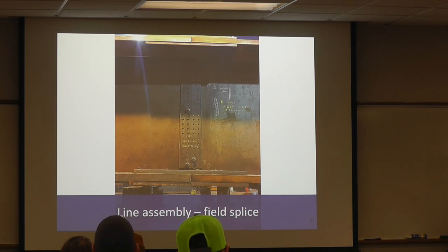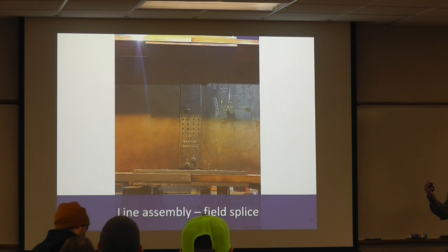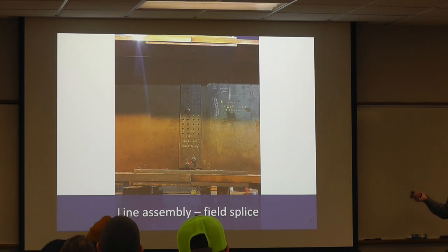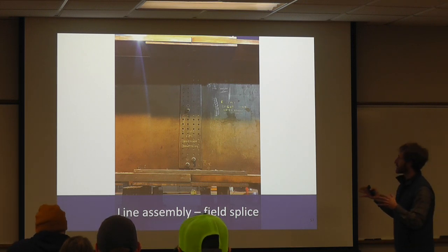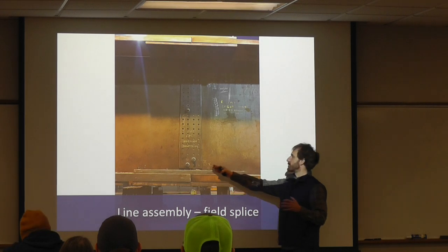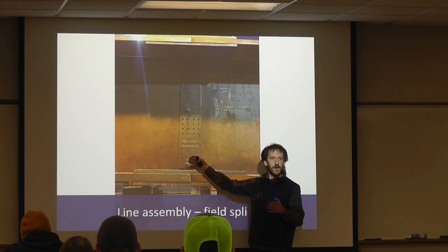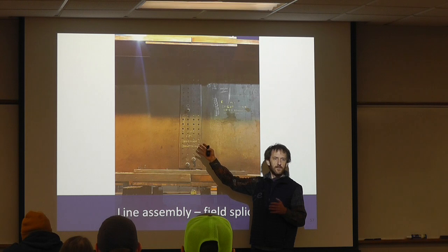Typically what fabricators do is their field splice plates, so this outer plate, is going to be drilled in some sort of CNC process, pretty precision. But then they're going to come through and with a couple select holes started to hold this in place, they're going to drill into the girder through the steel. So this is drilled literally in place, meaning that only these pieces are going to fit together. Now I highlight this because I was on a project once when they ship these splices, not all the holes are stuffed. Usually it's just a handful of them to keep them on there.